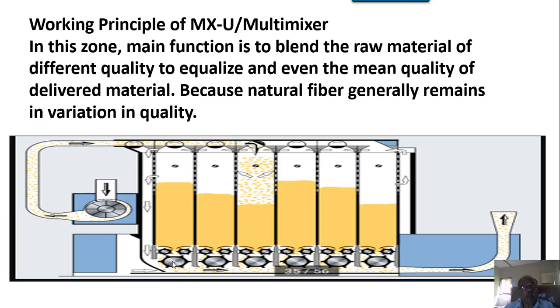And now at the bottom there is a conveyor, and after the treatment at each of these beaters in conjunction with the bars below them, the opened up material will be deposited on the conveyor at the bottom, and each chamber will go on dropping its material as the height is different in each chamber. So chances are increased that thorough mixture will take place, and then at the exit the material is sucked and taken to the next department.